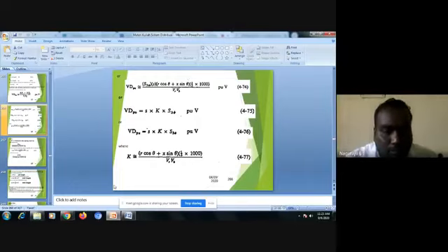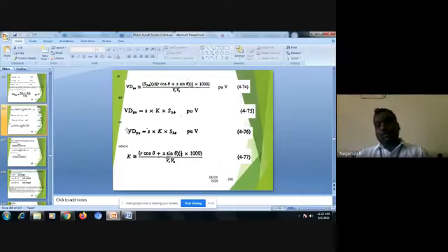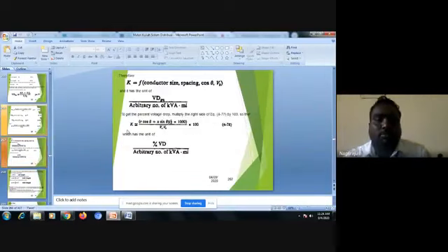Finally, I'll get the K value like this. I told you, voltage drop per unit is equal to the already existing kVA loading into K constant into three phase. This is in per unit volts. So K is a function of conductor size, spacing, power factor and base voltage.